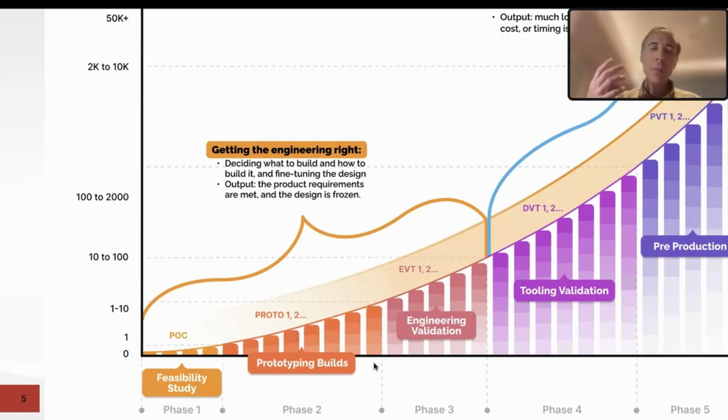In parallel, the engineering BOM gets more developed, richer, with more information. In some cases where high risks are identified, there has to be some work done on the compliance side, maybe some pre-testing, maybe design reviews, and the same thing for reliability. Sometimes that means requesting test reports from suppliers for critical-to-reliability components, or maybe doing your own highly accelerated life tests and these types of reliability tests. And there should also be a plan for how this custom design part is going to be made. What process and what surface treatment, etc.? What about this one? What about this one? There needs to be a plan.